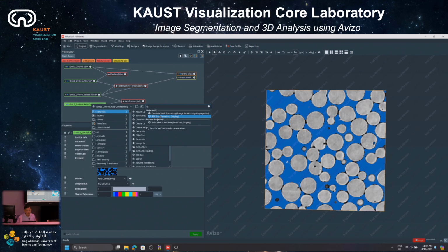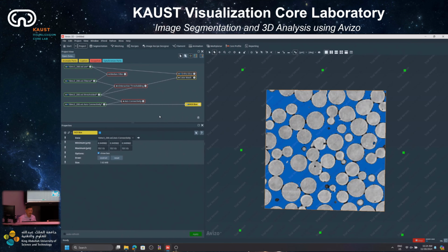So first I'm gonna select the ROI box, and here because it's in the perspective view, I can go quickly to the orthographic view. So this way I can see clearly. I'm gonna extract only the center part of the volume to work with. So I use the value, let's say, the same size in all directions, 85, and I know this value because I used it before, 473. So you can extract only the center or top volume.